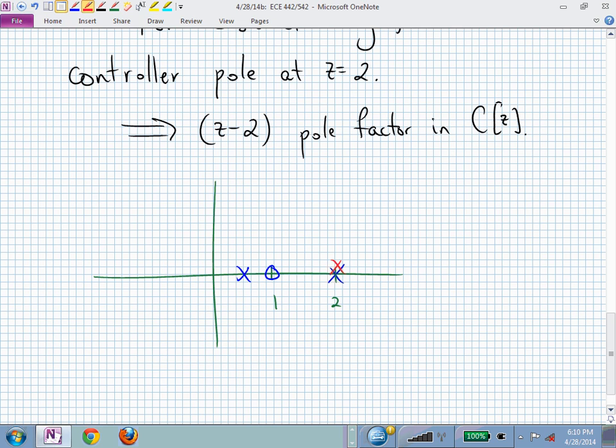Now what do you have? What's your pole zero excess? Now it's 2, isn't it? So how many infinite zeros do we have? 2. And when we have 2 infinite zeros, where do those angles live? 180 divided by that 2, isn't it? That's your fundamental angle at 90 degrees. And that then tells you how you're splitting the rest. So the other ones at -90 are at 270.